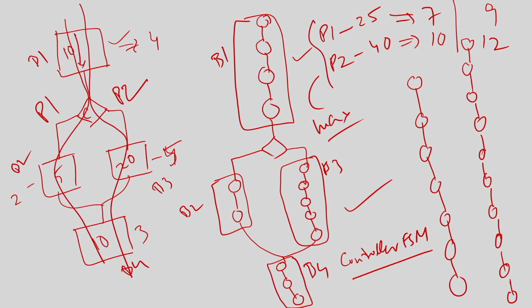How to combine these two paths together is something we are going to discuss in this class, but the basic approach is similar to the basic block approach, where we take one basic block at a time, schedule it, and then combine the results. Here you identify the paths, schedule the paths independently, and then combine the schedules of the paths, right. That is the overall path based scheduling algorithm.